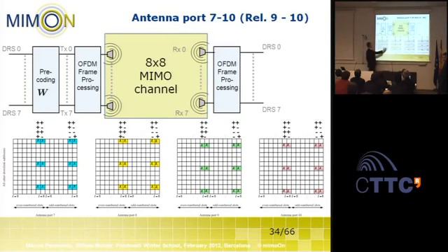So actually, you need to assume that the channel is approximately constant over the entire resource block, because it should not change over these 14 OFDM symbols. So that's quite a requirement: for 1 millisecond, the channel should be approximately constant. But the idea behind this is that if you use higher order MIMO, then you would only do this if you have favorable channel conditions. If you are moving in a high-speed train, nobody expects that you can achieve, let's say, 1 gigabit per second download.